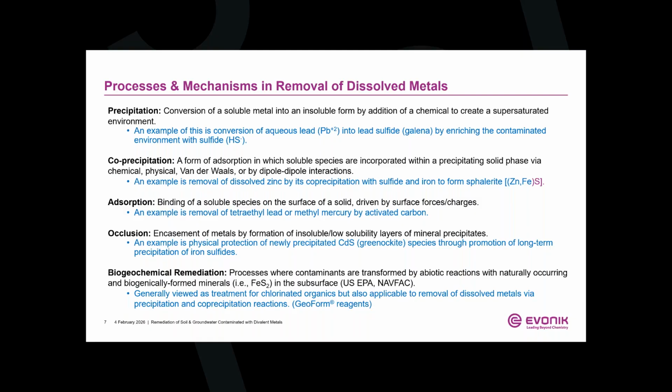and it's kind of locking these up by putting them underneath layers of other insoluble materials, and that can prevent resolubilization when Eh conditions change, or if you're in an aquifer that tends to acidify.